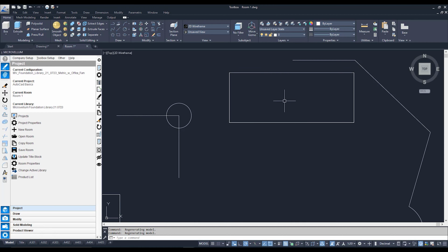So I'm going to first draw my 3D shape. So I'm going to use a polyline, so I'm going to go over here, and I'm going to specify some odd points. Just left clicking, just eyeballing it. Now I'm going to close this shape, and the easiest way to do that is in your command line, you can see the option to close the polyline. Hit that, and now it comes back to one shape.